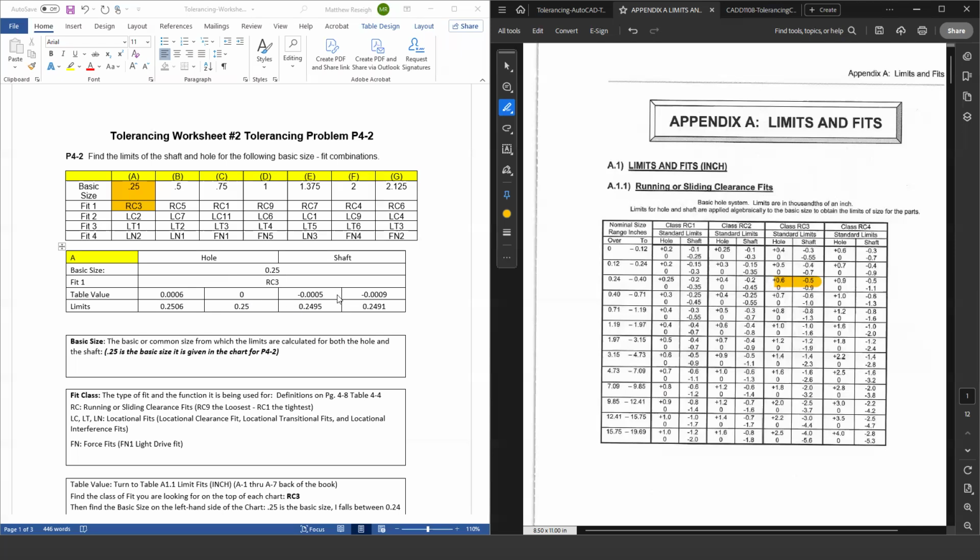Let me interpret what the shaft values are allowed to vary. Because what I'm looking at is how much they can vary, what the tolerance is. So the shaft one is going to be kind of a negative half a thousandth, 0.5 thousandths. So that's the first one I put in this column here. Negative 0.0005 is the same number as this right here. They totally shortened it.